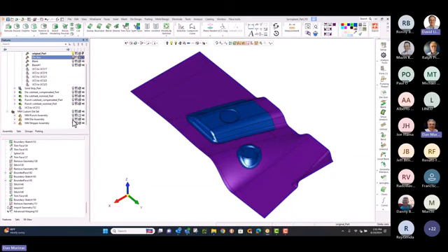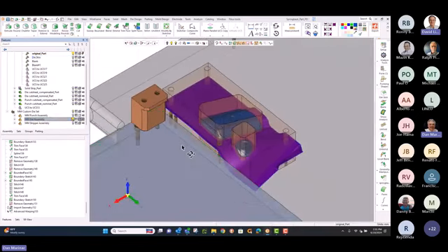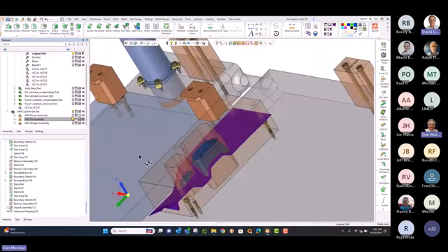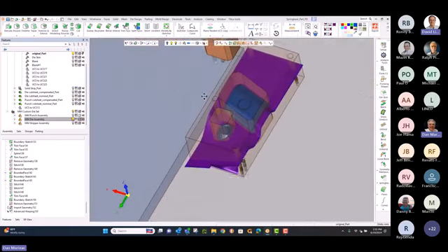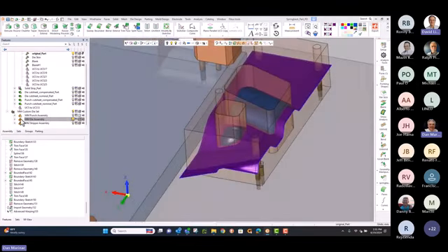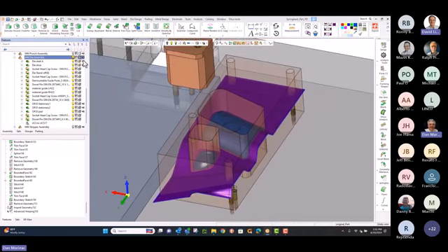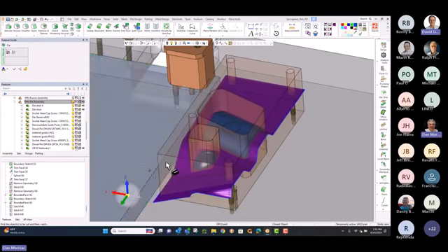All right, with that done, we've looked at the two simulation types we could use. Let's go back into our tool. Of course, Cimatron is software meant for tool design as well. And here we've got an already started die set. I've got some die and punch forms already in place. Now we need to get that compensated surface on it for the spring back.